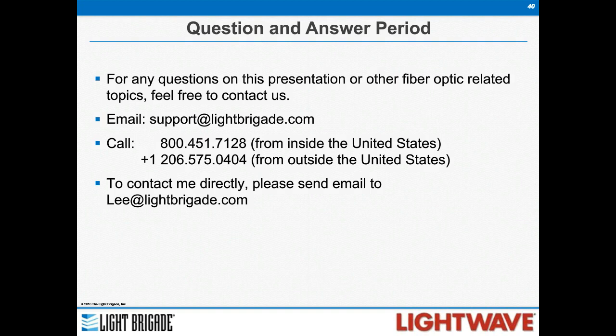What does a receive cable look like? Is it just a connected fiber jumper at the end? For OTDR testing, a receive cable should be similar to your launch cable. So it could be a fiber ring that's 100 meters or 150 meters connected to the other end, so you can clearly see where that last connection is, and then you should see that other length of fiber. It needs to be long enough so that it doesn't get lost in the noise and you can really detect that last connector. So we'd recommend something like 100 or 150 meters, just so you can assure that what you're looking at the very end is that last piece of cable.